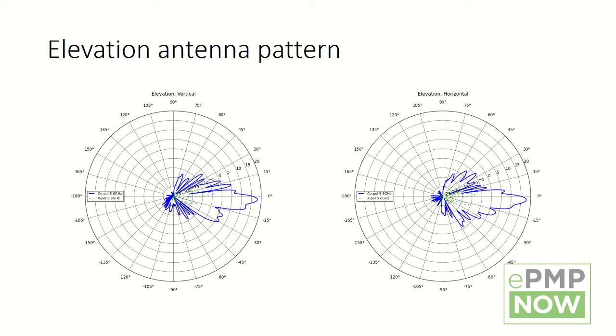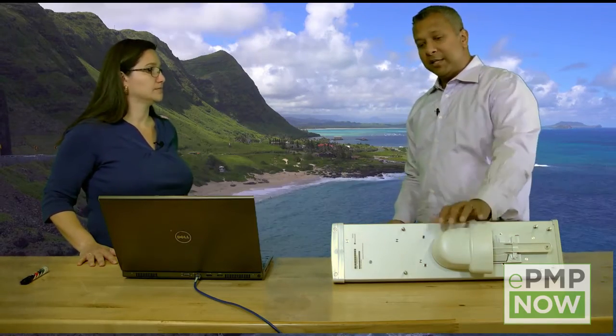But in vertical, I'm on a long tower. My AP and antenna is looking this way. I'm on top of a mountain, and I have subscribers really close by. If there's a null, meaning there's a deep gap in my coverage because I don't have energy, that means all of a sudden, even though that subscriber is so close, they're not going to get the performance they need. Correct. And that's where null fill comes in. So an antenna that does the best job of squeezing that balloon and is still able to provide coverage right below has good null fill. Correct.